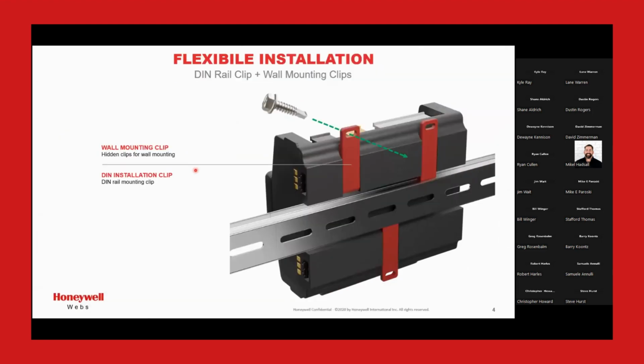They're all DIN rail mount, and this is pretty standard of new Honeywell controllers. You put the little red clips down to click on the DIN rail. If you physically yank them up a little bit, you've got to jerk on them kind of hard, you can extend them out far enough where you can put a screw through them. So we've got this neat little standardized way of either going DIN rail or panel mount. Some contractors didn't realize that these can be pulled high enough away from the plastic where you can use them as a mounting ear.